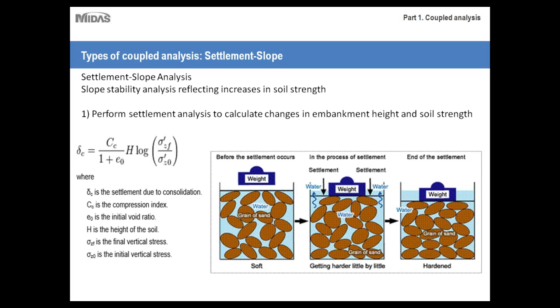As you can see, if you look to the right here, this is an exploded view of your clay particles as well as the water. As weight is pressed upon the clay, the water seeps out very slowly, and over time, that clay will begin to compact. Depending on the type of clay you have, you'll have certain amounts of settlement, as well as strengthening in the soil itself. That's another key thing to keep in mind: when clay is consolidated, first and foremost it compacts, so there's displacement, and second, the overall strength of it is increased as well.